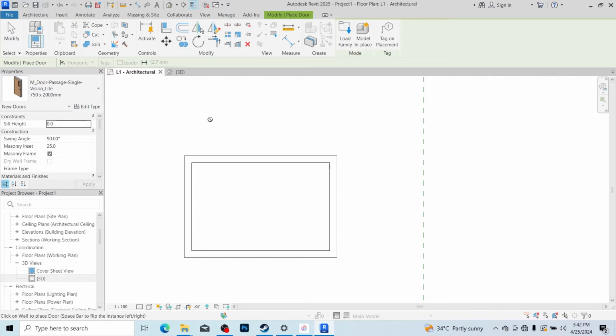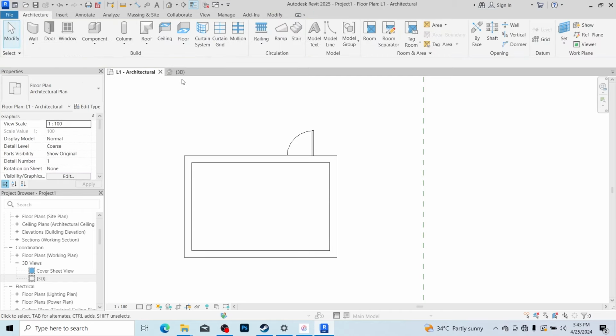And the beauty of Revit is that whenever you go ahead to include an element in any view at all, Revit actually updates it in every other view that you have in your project. So if I have a wall that has a door attached to it like this, there's our wall. You can change the position of this door by changing the dimensions here. But we're just going to press escape once and again, and then go over to 3D view, and then you